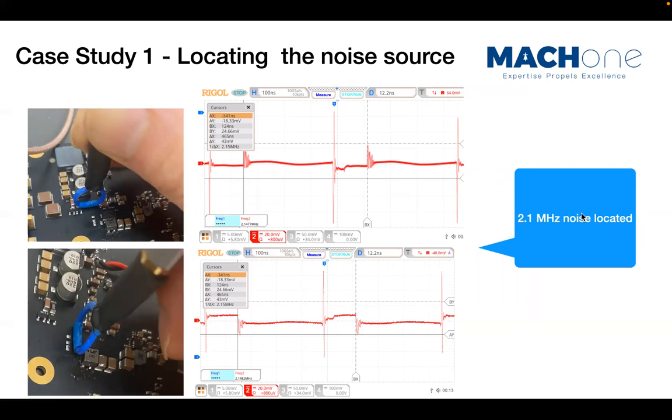We know the frequency range that could cause problems. So the next stage is to find which part of the circuit caused a particular issue. So we're introducing the magnetic field loop to locate the noise source. The technique is the same as we just discussed. Move a small loop alongside the PCB and I identify the spikes and I measure the frequency between the neighboring spikes.